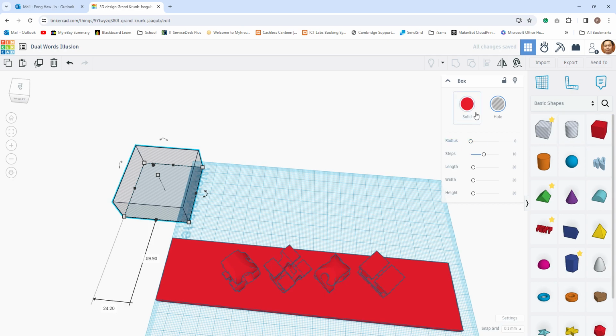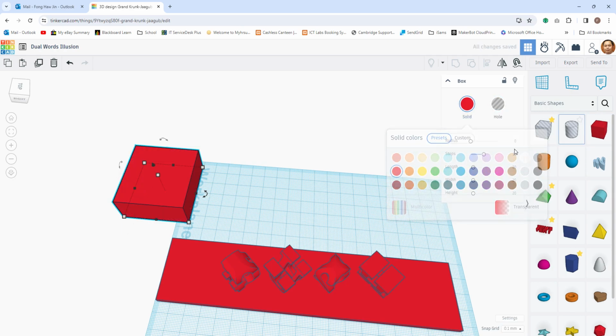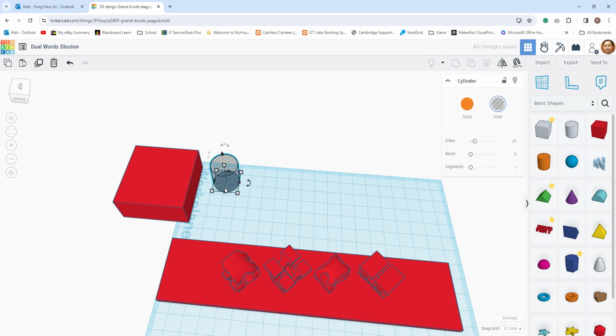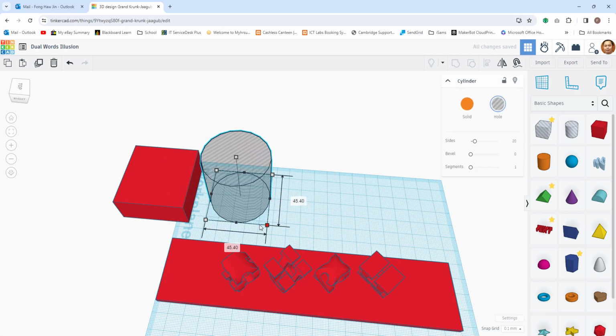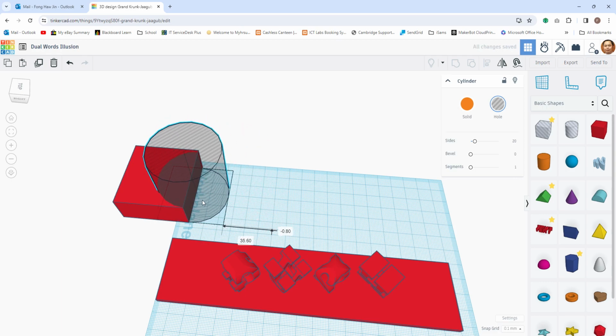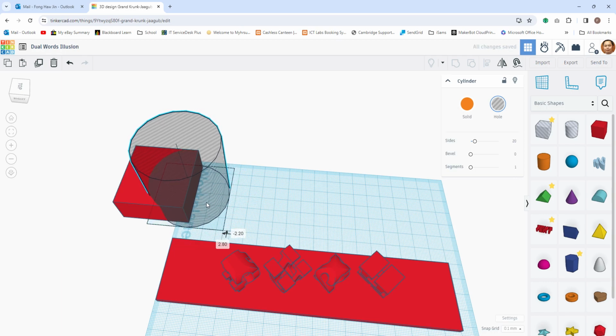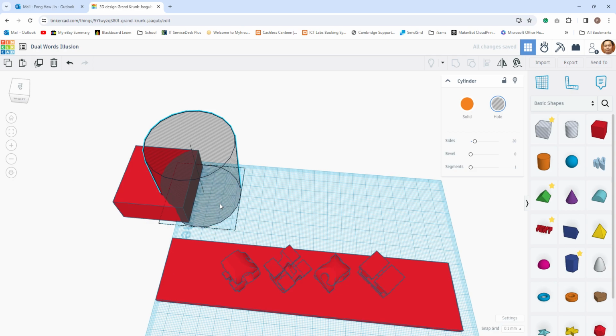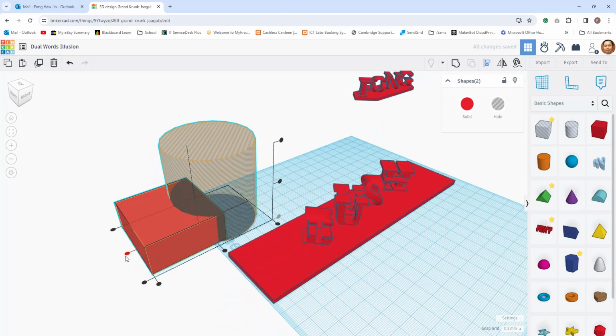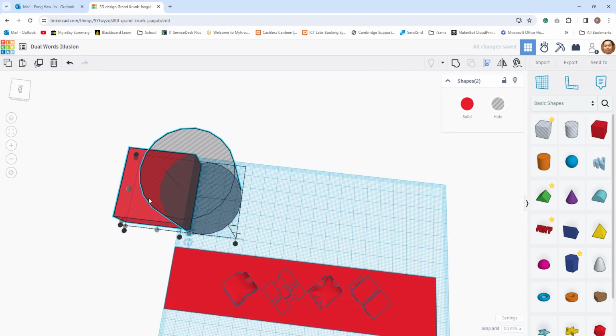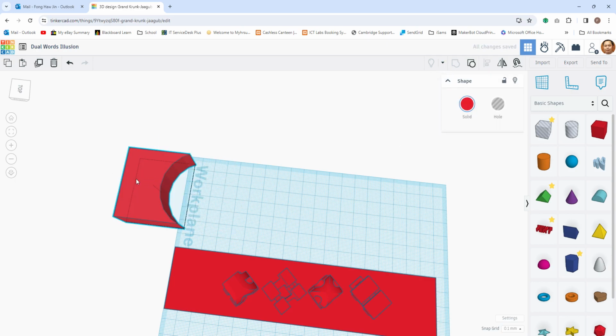What I would suggest is I will change this back to solid stage. Then I use another cylinder. Okay, hold down the shift key, make it big. Hold down the shift key, make it big first. Okay, then you make it slightly bigger. You cut. You can try using a different way. Okay, so using this one will be faster. Center. Okay, save our effort, save our time. Then you do a merge, cut. Okay, after you cut,